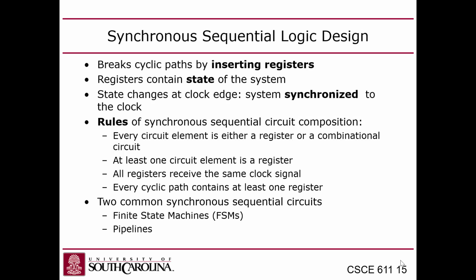This is something I can explain with the example I used earlier with the stall signal. So in your CPU, if your CPU fetches a branch, and when that branch instruction gets to the stage of the pipeline where it's resolved, determined if you should be taking the branch or not, you want to set a stall signal that will take effect in the next cycle, when the next instruction that appeared in the program after the branch reaches the stage where it otherwise would be evaluated, but we want to step on it, right?